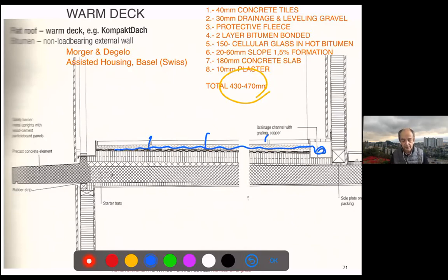But yes, for most garden roofs it's not necessary, but with that inverted layer, you will have the insulation always having additional protection to the waterproof, right? Because those roof gardens have a lot of weight, and that waterproofing will let it work much better. It's not anything in inverted roofs. You need to have a really waterproof insulation. You cannot use anything.